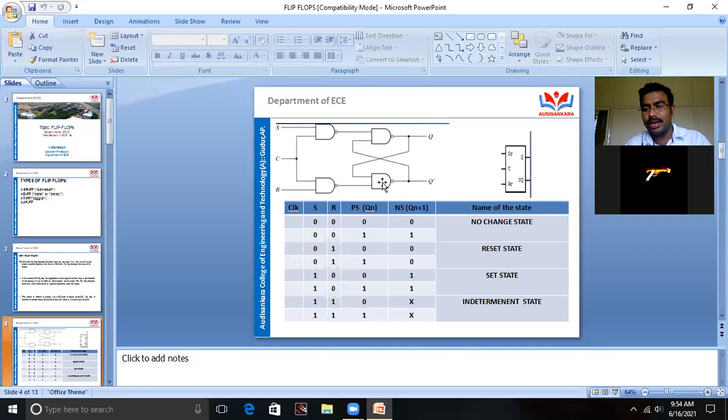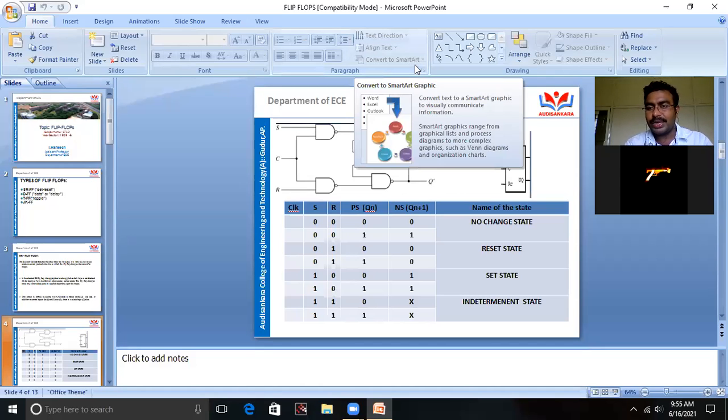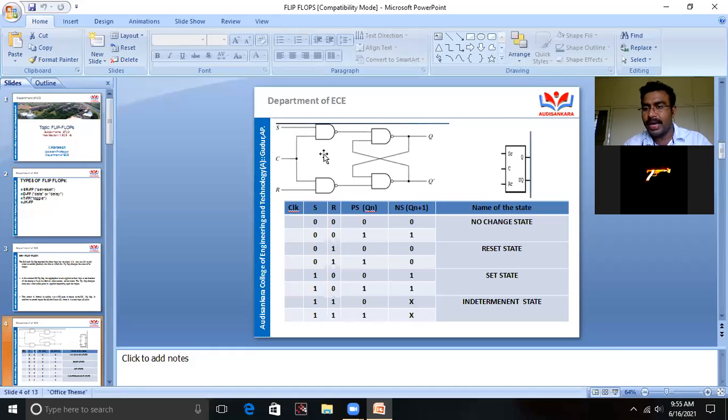This triggering is nothing but an extra input or extra voltage that we can supply to the given circuit to shift its state. Guys, I told you, suppose you give 0, 0 as input and get an output 0, then you give another input, 0, 1. By giving another input, the output cannot change. The output cannot change here, guys, unless you apply a trigger to the given circuit. That trigger will make sure your state changes according to the given input and previous state.